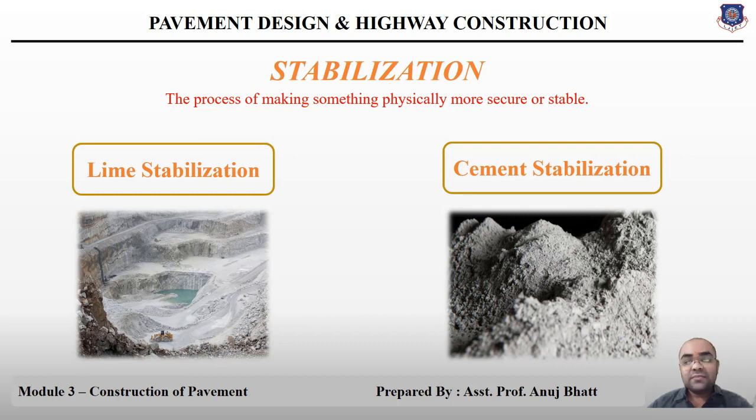In cement stabilization, the better the pulverization and the higher the degree of mixing, the higher the strength. The presence of unpulverized dry lumps of soil will reduce the strength as well as the durability of the soil mass.